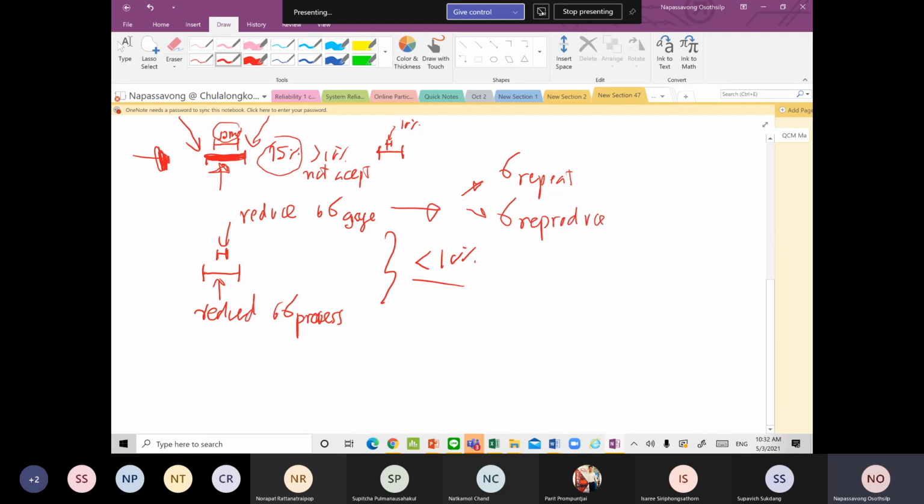You can train operators to be more consistent. You can check the gauge so that it gives higher repeatability performance. This kind of thing improves the precision of the measurement system, to have it ready, or good enough, to measure the variation of the process that is now small.